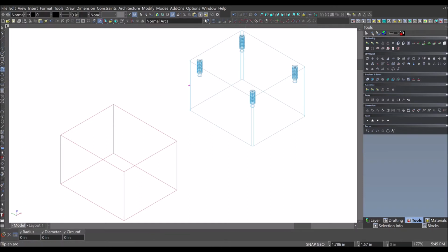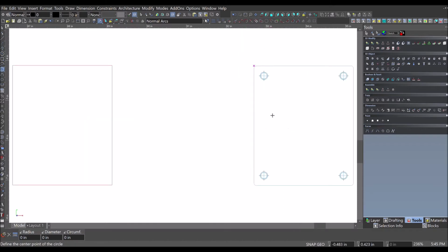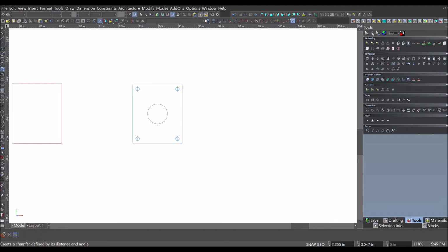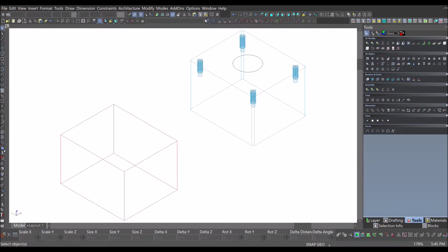So now we got our 10-32 bolt holes in there, and we got a 0.060 radius on the edges. Now I'm going to drop a 1-inch diameter hole through the part from the top to the bottom, and then I'll do some work on the dimensioning, show you how the dimensioning works and how the drafting palette in TurboCAD works.